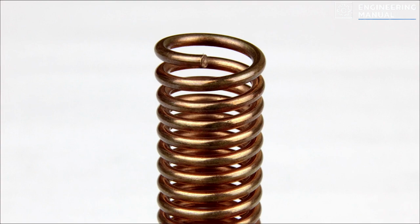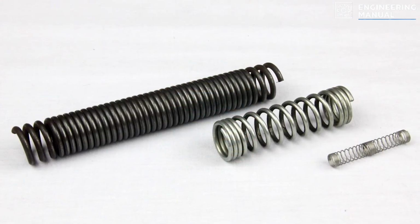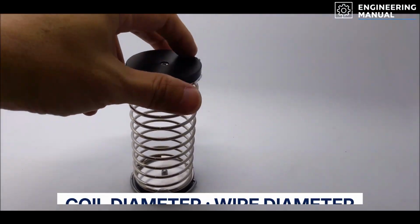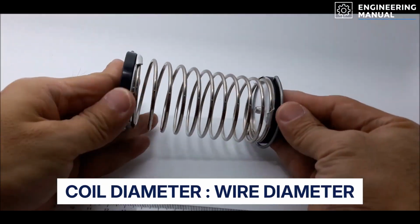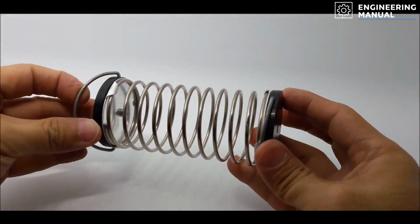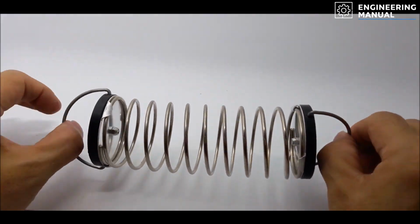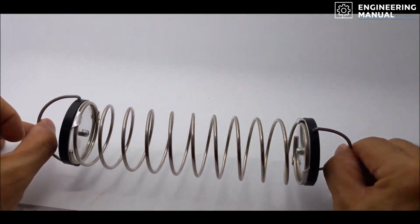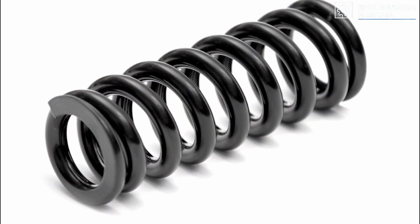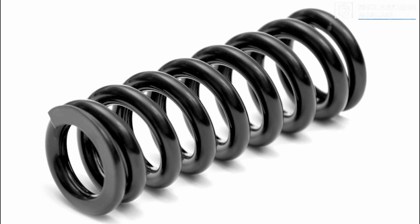under cyclic loading. The key design parameter is the spring index, the ratio of coil diameter to wire diameter. Too low, and stress concentration increases due to tight curvature. Too high, and the spring becomes increasingly susceptible to lateral buckling and loses manufacturability control during coiling.